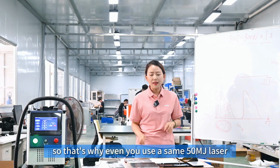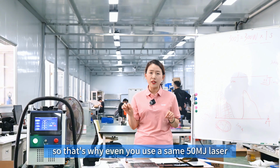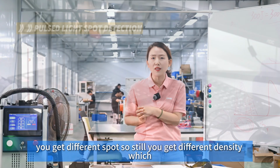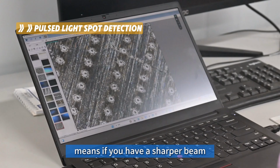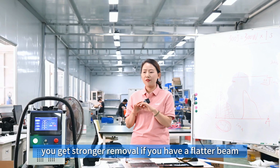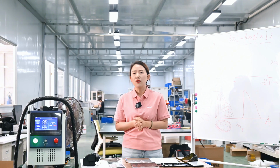That's why even if you use the same 50 millijoule laser, when you come to the point on the material, you get different spots. So you get different density, which means if you have a sharper beam, you get a stronger removal. If you have a flatter beam, you get a soft removal.